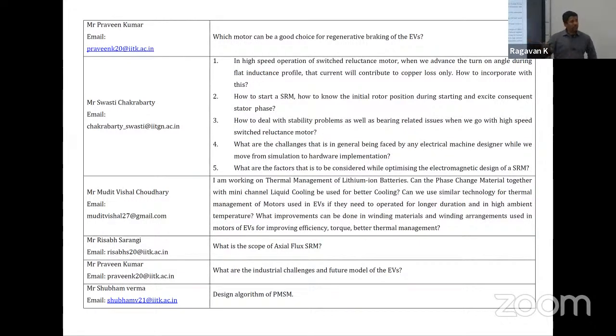But in terms of the design stage, you need to have a bearing that has a lubricant that can handle those speeds. Otherwise, the lubricant can harden. It basically gets very gummy or hard, and it'll start to then crack and break.